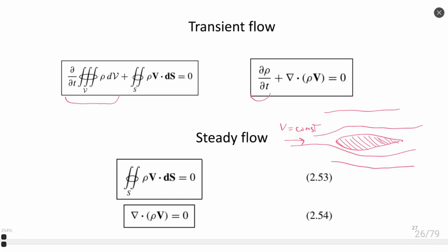So all time derivatives, not just from the continuity equation, but from other equations also, are equal to zero when the flow is stabilized. These parts of the equations are equal to zero, and it means that we can use the stationary form of the flow equations. Stationary equations are much simpler than transient, and usually they might have an analytical solution for some particular cases, at least.